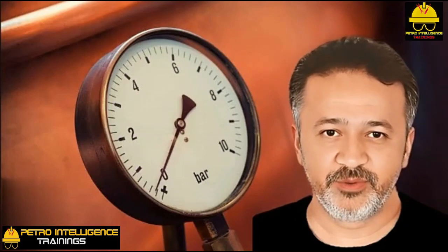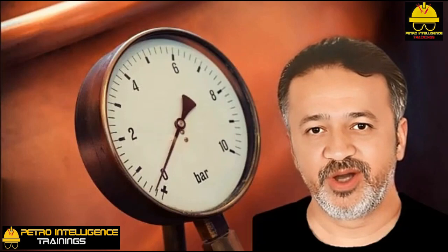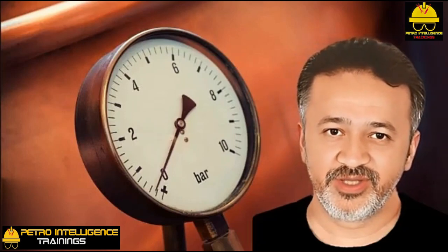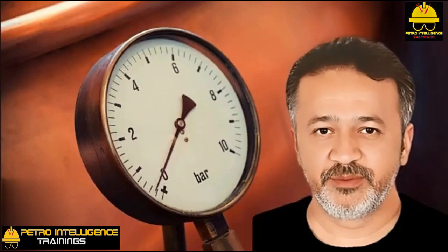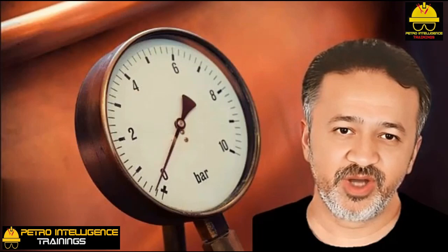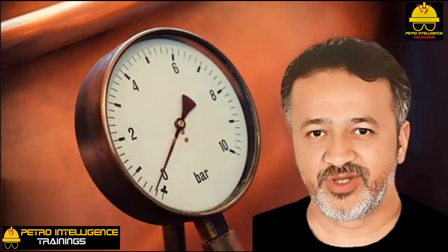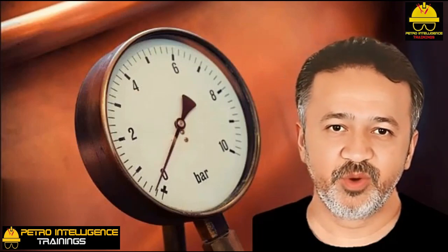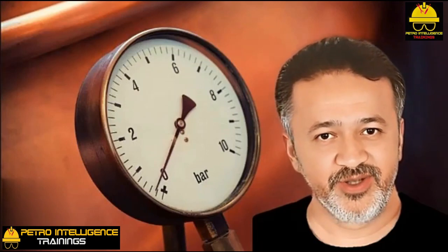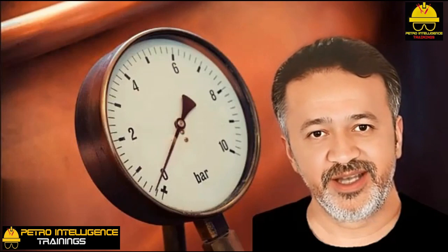An ordinary vacuum pressure gauge reads 0 inches of mercury in Denver and in New Orleans, because although these cities are at different altitudes, the vacuum pressure gauge compares system pressure only with ambient pressure. But a vacuum pressure gauge reading 25 inches Hg in New Orleans would correspond to a poor vacuum of 5 inches Hg absolute pressure, 30 inches Hg minus 25 inches Hg.